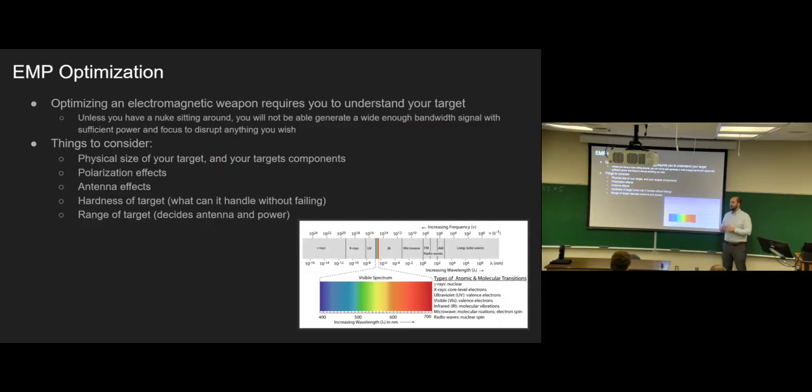We have in-country fabs whose sole purpose is to design and fabricate what are called hardened components. Components that can handle gamma rays, X-rays, electromagnetic pulses, that kind of stuff. So we have special techniques, whether it be through shielding the component, whether it be through special fabrication processes, that can drastically improve their survivability under adverse conditions. So the answer is yes, and there's quite a lot of money made in that field.